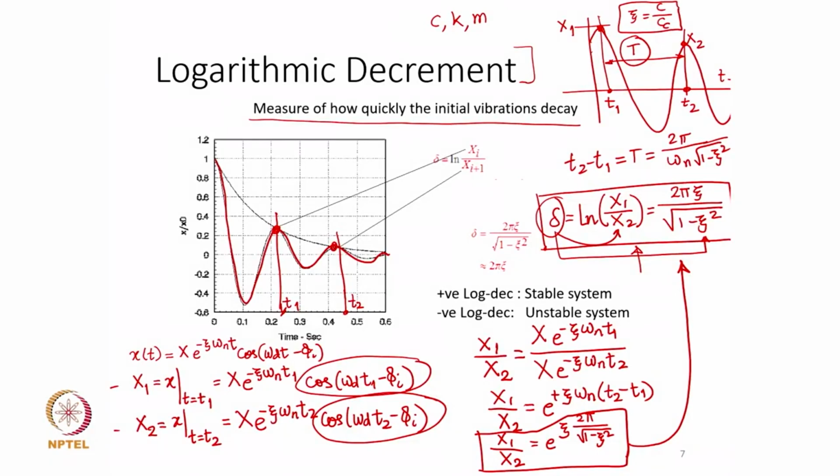So, one of the common practical expressions widely used ignores the denominator here, because it is going to be very close to 1. By using this simple means, if I measure the response and get this delta value, from this relationship I get the value of the damping factor of the system. This expression is valid for zeta less than 0.4 or so.